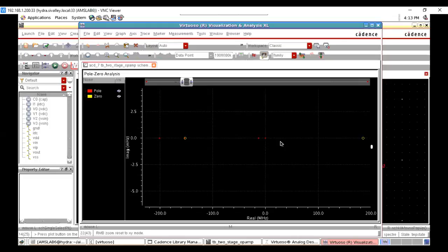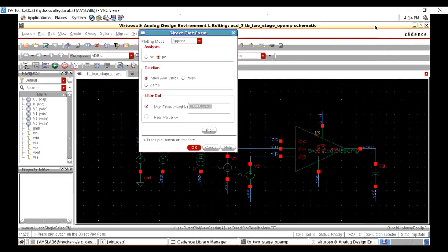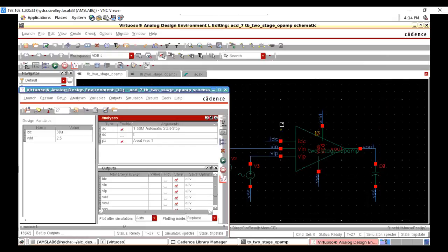Yeah, so I think we saw the DC analysis and AC analysis, and also the pole zero analysis. So we came to know that there is a zero causing an issue for stability, that I'm getting the phase margin of 20 degrees only, instead of 60 degrees. So that we have to fix here, right? This is the point where we left, right? Or anything else?